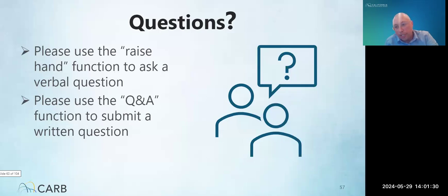There's currently three technology vendors that are pursuing CARB verification at this time. The CARB verification process is fairly rigorous. It takes some time. There's a number of rounds of emissions testing, as well as a 1,000-hour durability demonstration requirement of in-use operation. So DPFs should be forthcoming, but none are commercially available at this time.